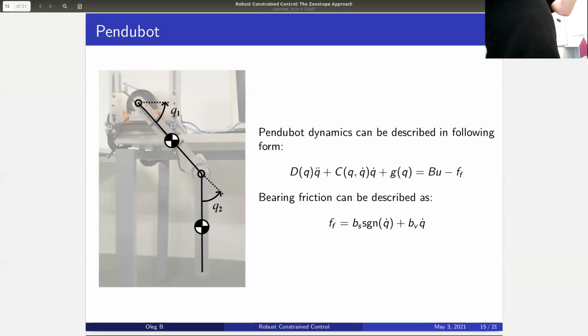You cannot find contraction because some of the Zonotopes will increase. Okay. Then this certainly can give you... The question was, when you already implement this and you give some specifications, so you have a nominal trajectory, you have a number of LTV matrices, and so on. What does the algorithm provide you? It provides you these feedback gains and the Zonotopes around the trajectory which you can reach, right?